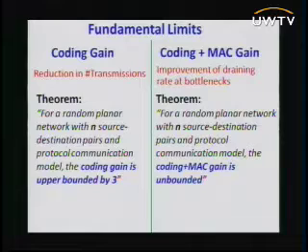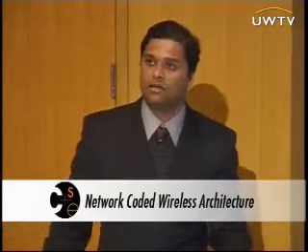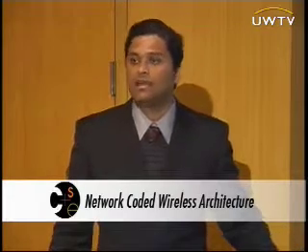So the coding gain is a factor of 3. You're reducing the number of transmissions in the network by a factor of 3x. Now, is the amount of extra power you spend more than this 3x gain you're receiving, because this is how many fewer transmissions you're already making? I would argue that the energy savings you get from reducing the number of transmissions is going to be significantly higher than the amount of energy you need to spend to build these components, especially because packet transmission is probably the biggest consumer of power. Running these radios itself is not that much power. And this has actually been analyzed by subsequent work once we published this paper, and I can point you to that work.